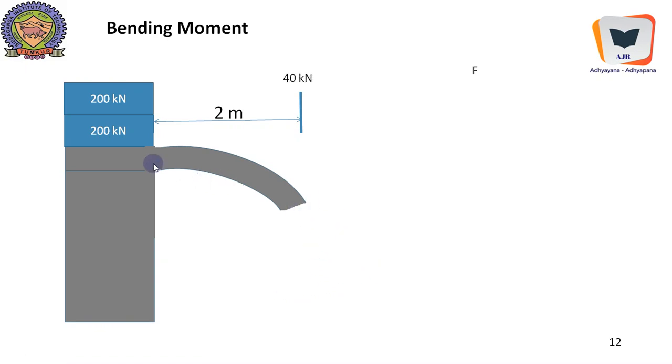And in a typical cantilever beam, we will see top tension, bottom compression, convexity upwards, concavity downwards. A fiber over here at the top will be elongated, and a fiber over here will be compressed. We can check this by putting some glue in our palm and allowing it to dry. And if we bend this palm, we will feel some kind of an excruciating pain at the top of the palm, while the fatal lines will close at the bottom.